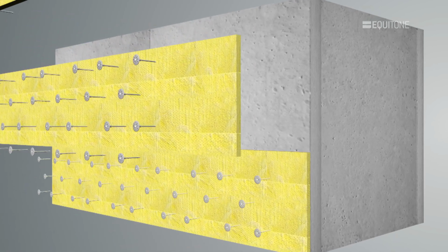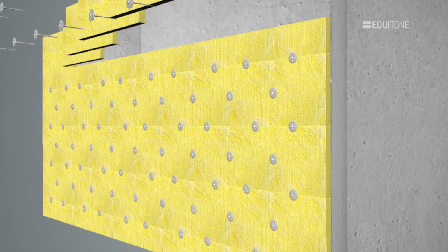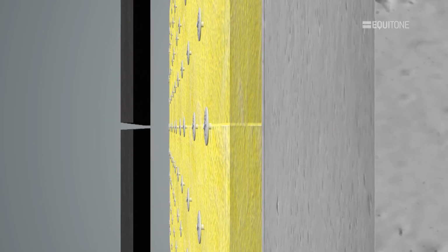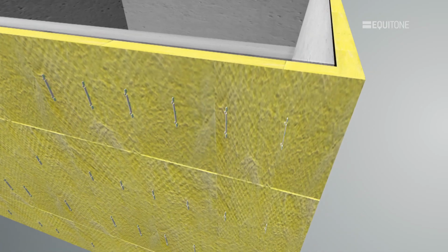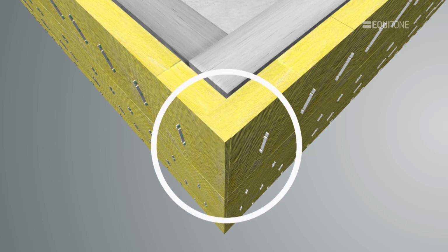Whichever insulation board is chosen, they must all be securely fixed to the structure, which is normally with special fastenings. Over time, the insulation must not sag or bulge out to block the air cavity. It is important that the insulation has no gaps at its joints and fits tightly around the subconstruction to reduce heat loss.